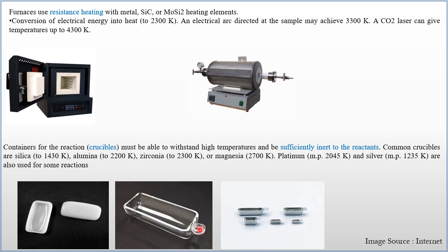Since you have this ring, you can push and pull the boat using one long steel rod which is bent at a certain edge, because otherwise how will you put your material in this tubular furnace? That is why this ring is there. And if you are using a box furnace, you can place a simple boat directly here.